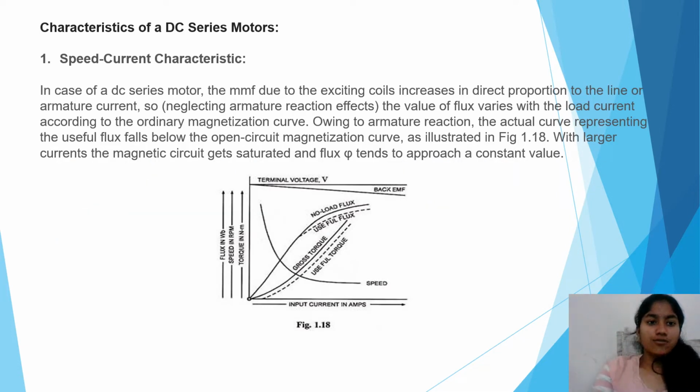First of all, what is a DC series motor? A series DC motor connects the armature and field windings in series with a common DC power source. The motor speed varies as a non-linear function of load torque and armature current. Current is common to both the stator and rotor, yielding current square.